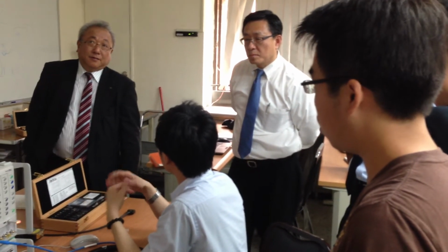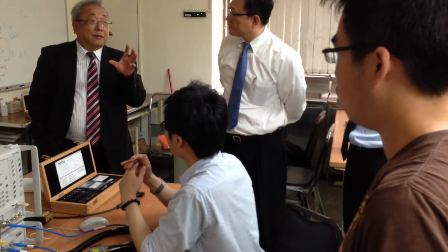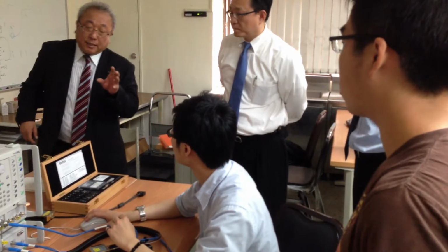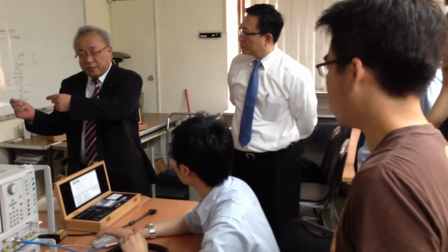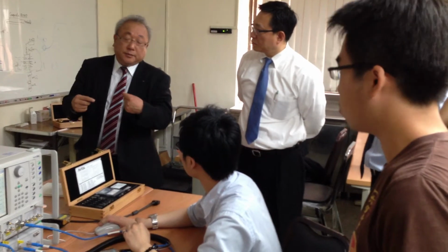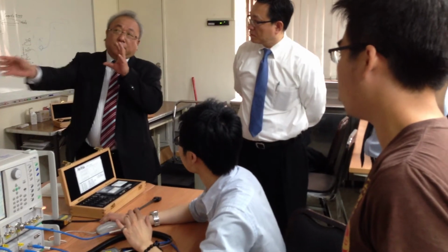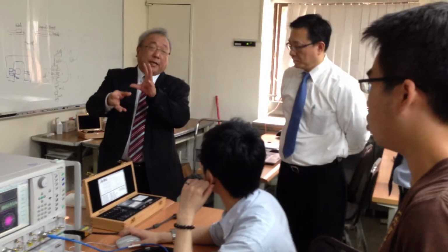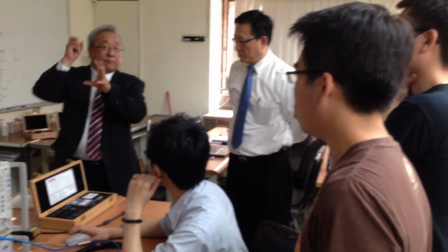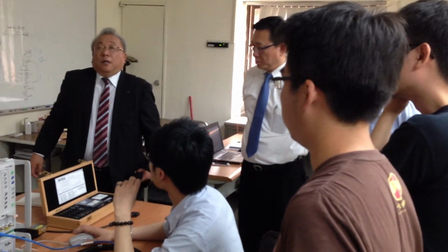It's using the S21 data only. It reads that data from the S2P file format, because the S2P file format indicates on the header the frequency points or something like that, and where the S21 is. Then I can easily pick up the S21 data. So in the conversion, the S11 or S22 are not calculated in the noise figure. Only S21 is calculated.